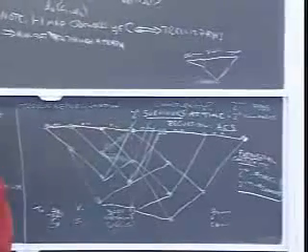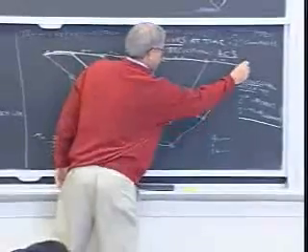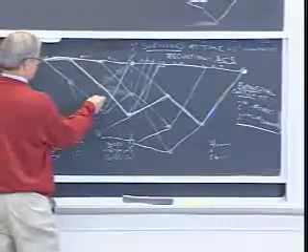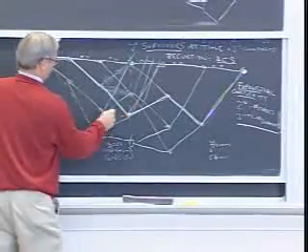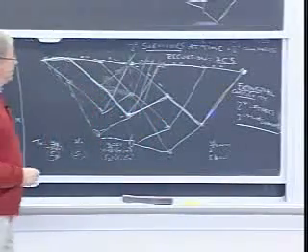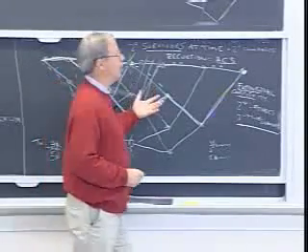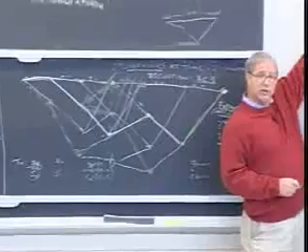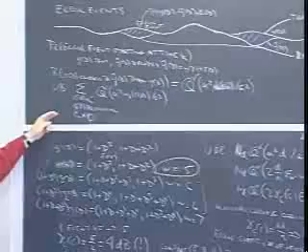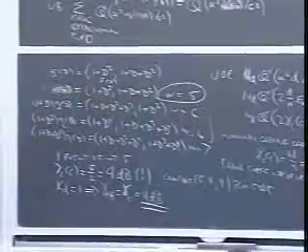Here's the transmitted path. Suppose I try to find another path that diverges from it. Here's one, comes back to it. Here's another one that comes back to it. I say the minimum length of time it could take is nu plus 1. Why? Because the difference between these two paths is itself a code sequence, is therefore a non-zero polynomial multiple of g of D. Okay, same argument.